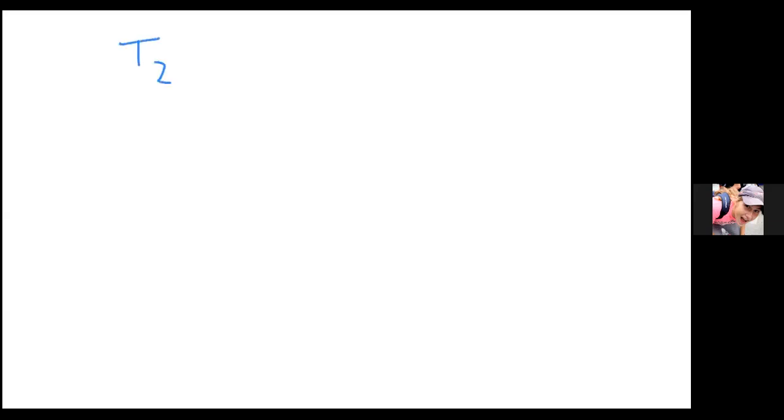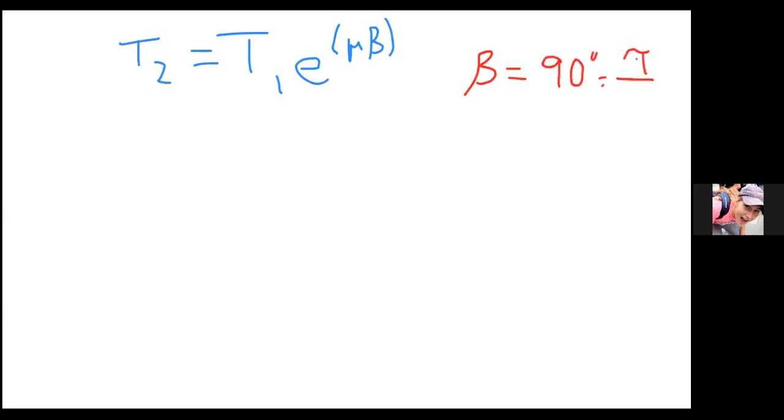friction, from my convention we would say T2 is equal to T1 e to the mu beta, right? Where mu is a coefficient of friction, beta is the angle. In this case, beta is easy because it's just 90 degrees or pi over 2 radians. Because remember, we do have to plug in radians here. And they told us what mu is. They said mu is equal to 0.35.